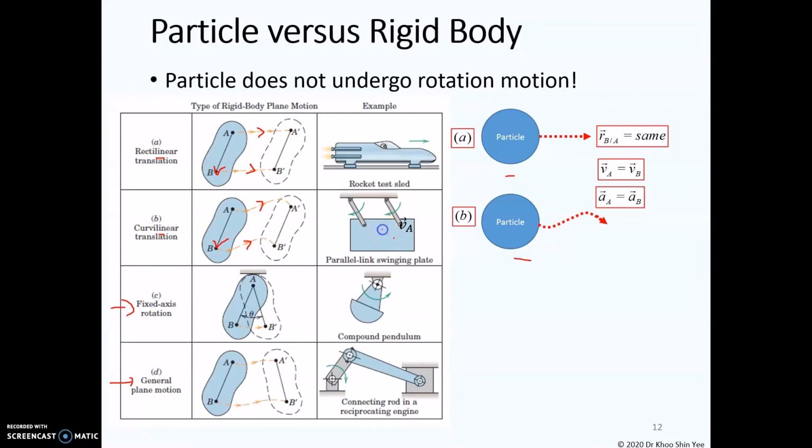For example, you draw 2 points randomly on this rigid body, form the relative displacement, and observe the movement of the displacement vector. If the vector doesn't change its direction or its length, then we say the relative displacement is the same during the motion. If the relative displacement remains the same during the motion, then the velocity and acceleration are equally the same at all the points in the rigid body. Therefore, we can simplify this problem into a particle motion.